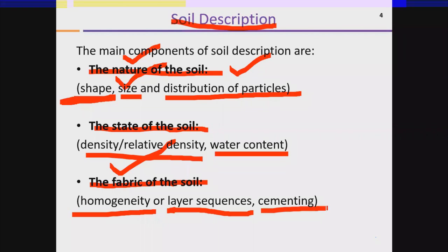You can also categorize the soil system based on cementitious properties. If the soil system has some cementitious properties, then the soil will be categorized as cementing in nature. And if the soil does not have any cementitious properties, then it will be categorized as non-cementing. For example, if you mix water with clay, its properties will change and it will become cementing in nature. After drying, this clay will achieve some good strength. But vice versa for sand. If you mix water with sand, it will not change its cementitious properties, and after drying it will become grains of sand again. So these are a few parameters with the help of which you can categorize your soil system.